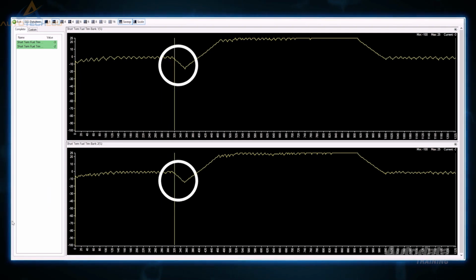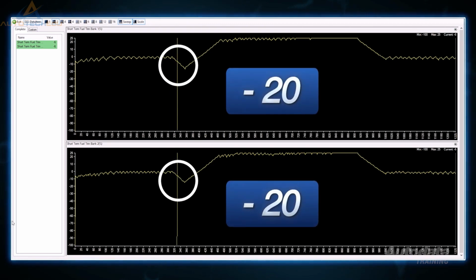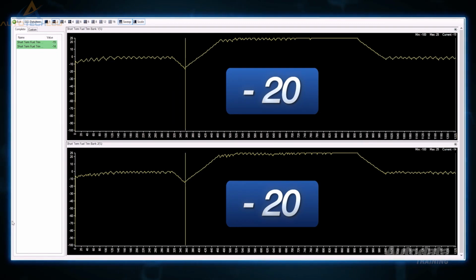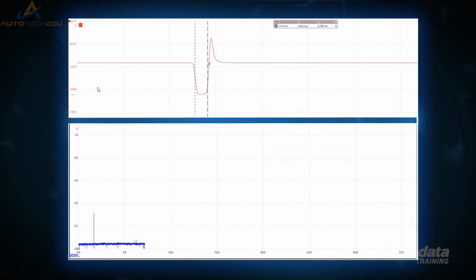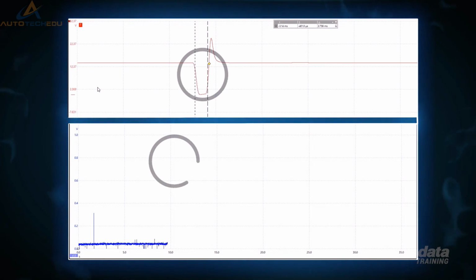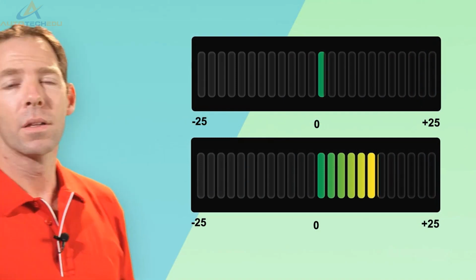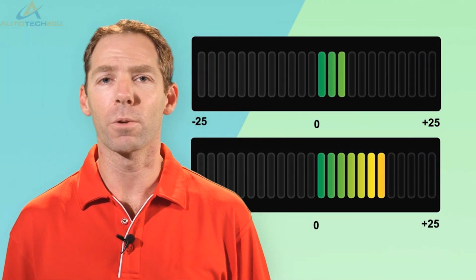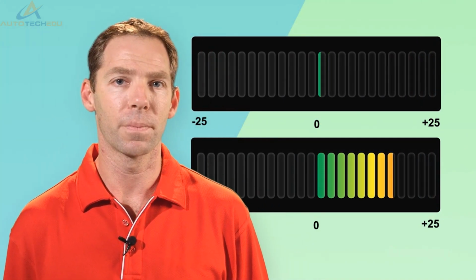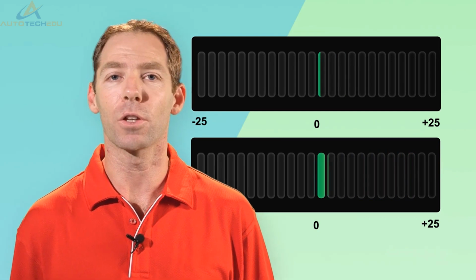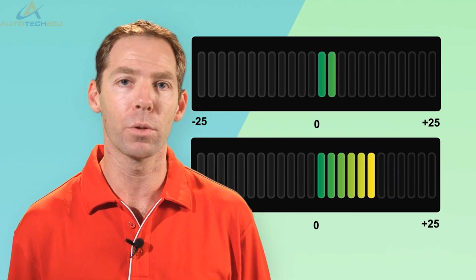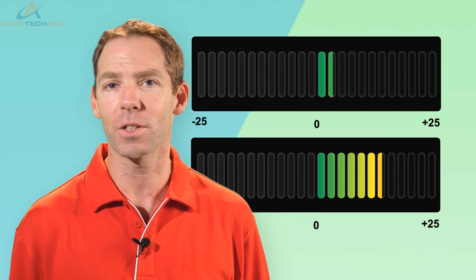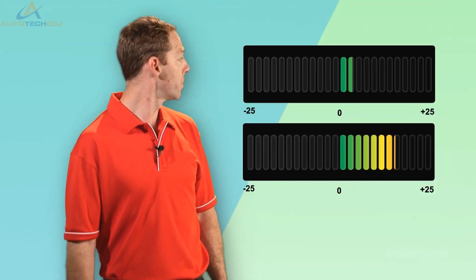There will be a time delay before there is any reaction at the injector, while the ECM decides whether this is a trend or a momentary change. This can be seen on the oscilloscope as the injector pulse width is now reduced. These trims can often be referred to as adaptive strategies, meaning the ECM can learn or adapt to minor problems or wear without sacrificing engine output.